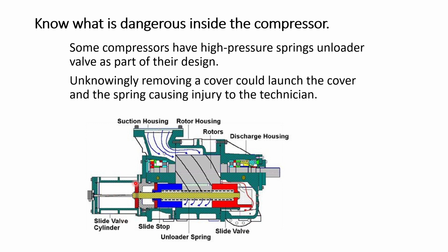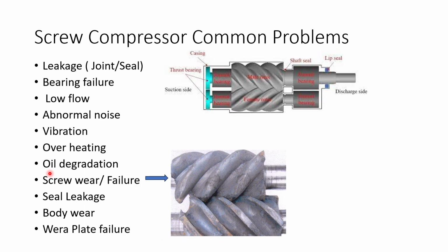This is the sliding valve. This is inlet, outlet. This is the sliding valve. So if he opens it suddenly, the spring will push everything out and he will get injured. So the technician needs to take care of this.